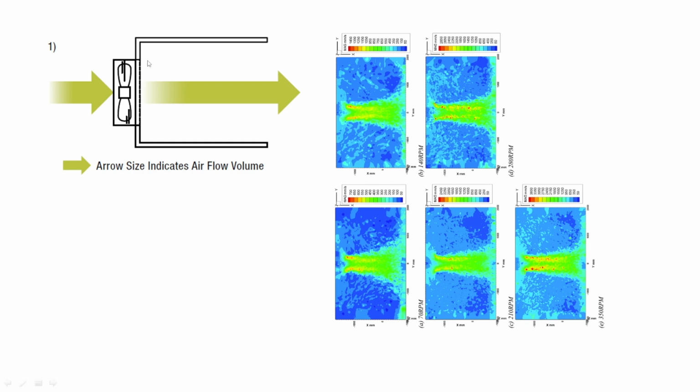The fan is blowing air down the tube. If the fan is the same size as the tube, there's no room for the air to expand if the fan has a tendency to blow air off to the sides. So all the air travels down the tube. But the problem is, if the air is trying to go sideways, it reflects off the walls, creating an area of slower moving air in a larger boundary layer along the walls. This slows down the air, but not at the same rate that the case simulation test indicates.